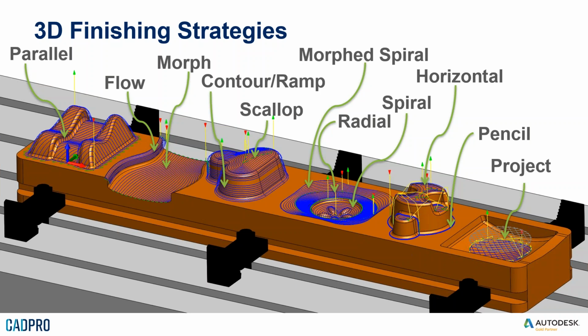Most of the toolpaths on screen here will convert the model into an STL, which is a faceted mesh made up of triangles. When you understand that and how it interacts with boundaries when you're doing your 3D surfacing, you'll see some noise appear in the toolpath in some situations, which is fine and is a standard feature of most CAM systems.